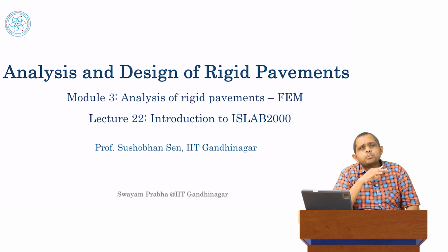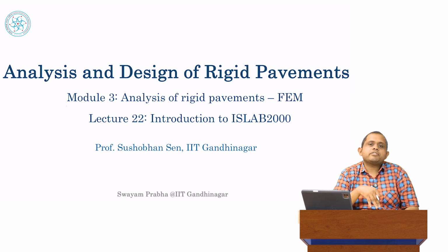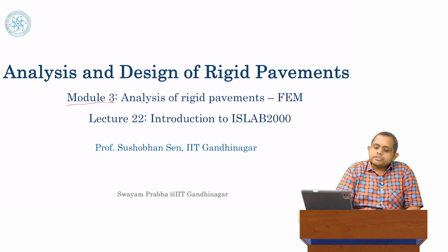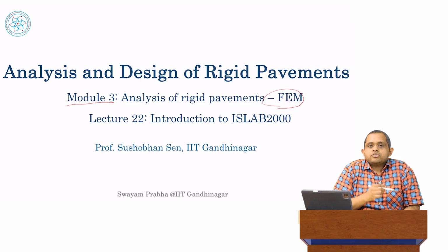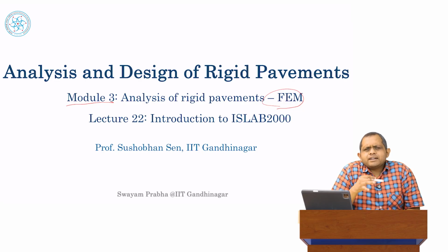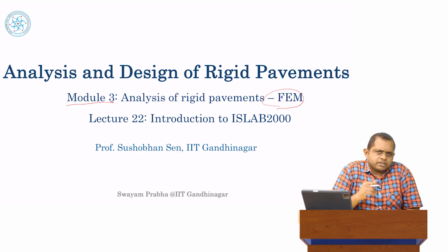And that's why, probably around the 1990s, particularly when digital computers started coming into commercial applications or more amateurish applications, new methods were used to analyze rigid pavements. And that new method, numerical methods, in particular the finite element method, has been our topic for Module 3. So in Module 3, we were looking at analysis of rigid pavements using the finite element method. The finite element method is one, but a very good one, numerical method. There are other numerical methods also.